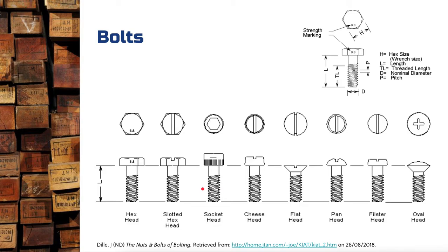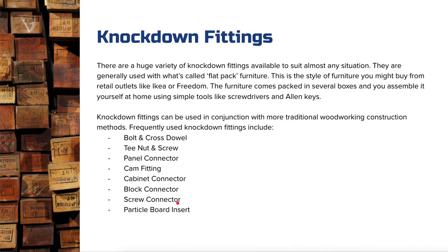The main difference here, there is no tip, so no pointy tip. It's a flat end. And that's because bolts are not designed to be self-driving into a material. You definitely drill a clearance hole for a bolt the whole way through, and the nut on the other end is what holds the pieces together. Okay, so key differences there. The other thing that you'll note is that the thread on a bolt is much smaller and less sharp to touch than you would experience in a screw, because it doesn't need to slice into timber grain. It just needs to have the nut slip over it and hold into position.